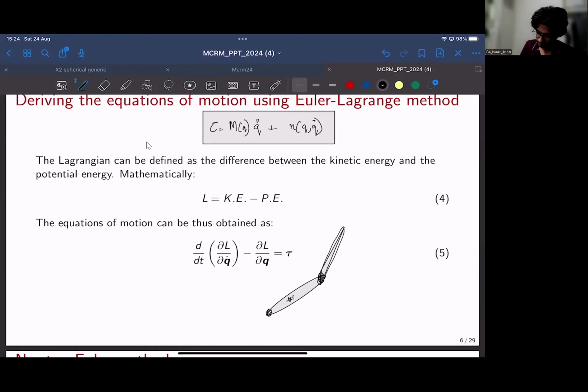So this is link 1, this is link 2. It's well known that this is a planar manipulator. So the coordinates of forces or moments that we need to consider for a planar robot are the forces in X and Y directions and the moment about this Z direction. So this is only a small example. It applies to a manipulator in large scales.